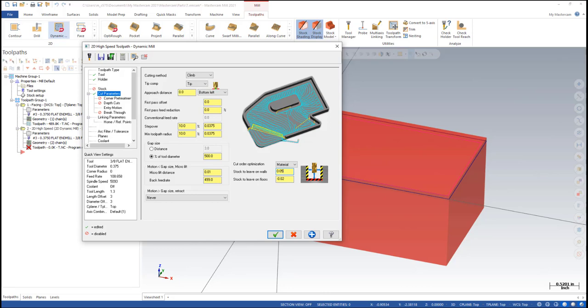To finish it, you want to use a proper contour that will tell it, like if it's a straight line like what we're working with here, it's 4 straight lines, it should be moving in a single straight line. So your movement command on your controller should be 1 line until it gets from here to here, and dynamic motion is not going to give that to you. So we'll leave a little bit of stock. We'll leave, say, 15 thousandths, just enough for a contour to come back and clean it up.